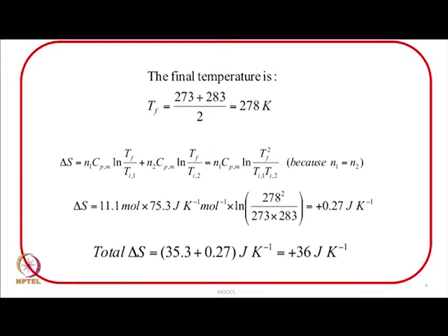Although the problem is a bit lengthy, it does explain how to account for the changes in entropy. Remember that during the process of mixing of ice with water which is at higher than room temperature, the first step is that the ice has to melt, it has to go to liquid water, and that is a phase transition, and we should not miss any phase transition.